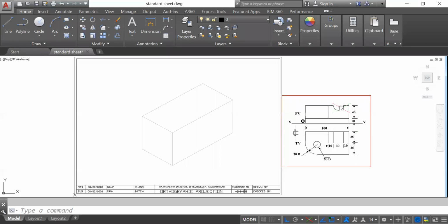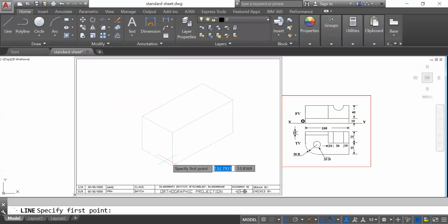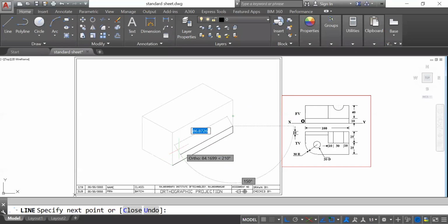Now I'll start with this background plate first. Okay, so that base plate, let us consider 10 mm. So I will start with this 10 mm. I'll check this. Then I can start with this 10 mm, with the Control E button, or you can start with this one because this is throughout, right? So Control E and then 10 mm, and then this side 100, and then I will connect it.